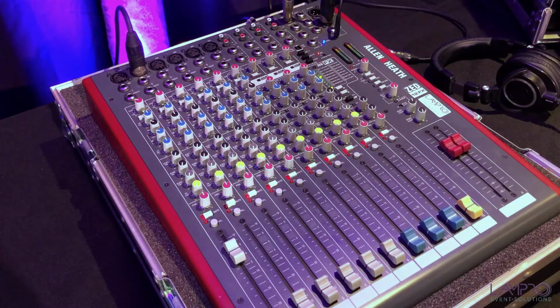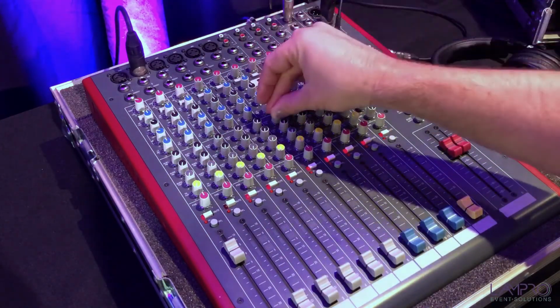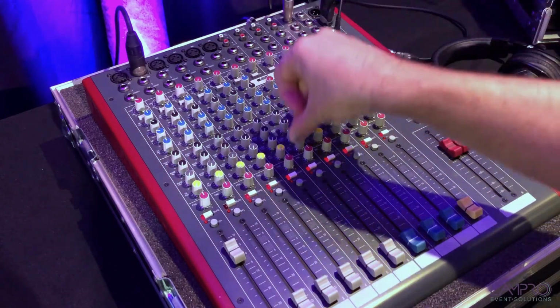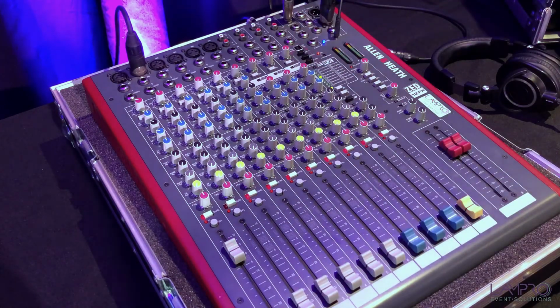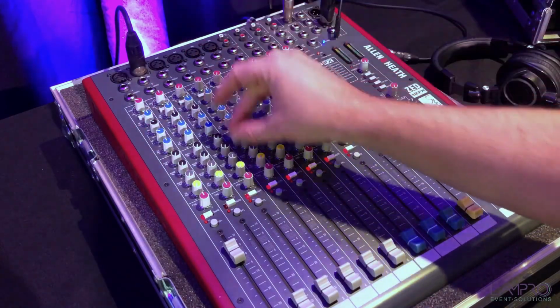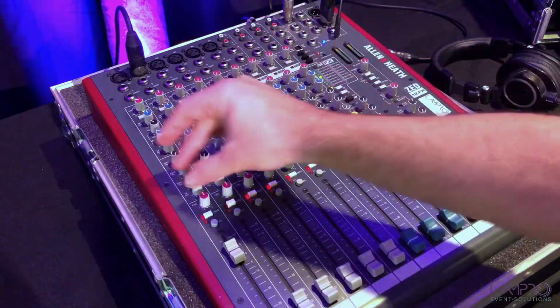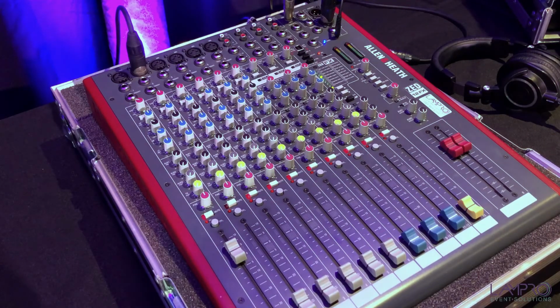Next, we'll have a look at the auxiliary section on the mixing console. Here we've got two pre-fade auxiliaries, namely aux1 and aux2, and we've got two post-fade auxiliaries, namely aux3, and the effects post-fade auxiliary that is specially assigned to the built-in effects unit. Traditionally, you'll always use your pre-fade auxiliaries, aux1 and aux2, for stage monitors that will not be affected by the channel's fader, and aux3 or post-fade auxiliaries will be used with recording devices that will be affected by the channel's fader. I'm quickly going to give you a demonstration of what the different auxes sound and work like.